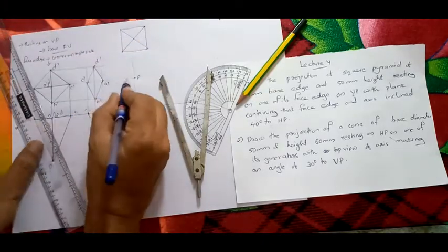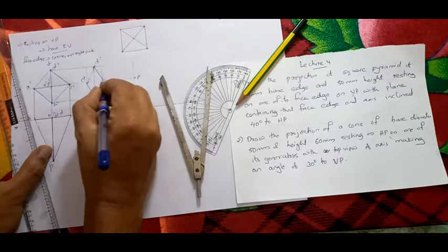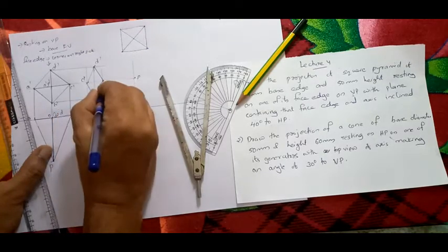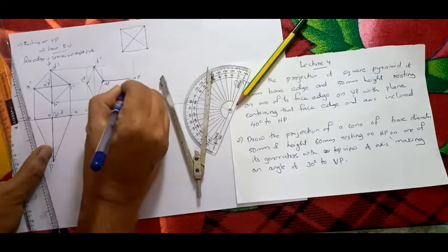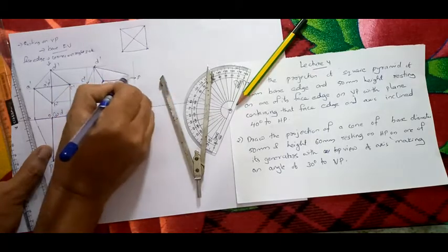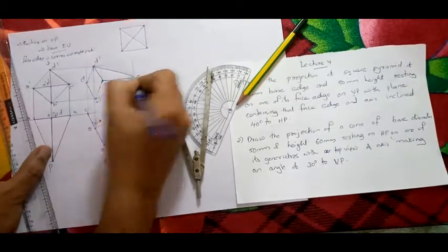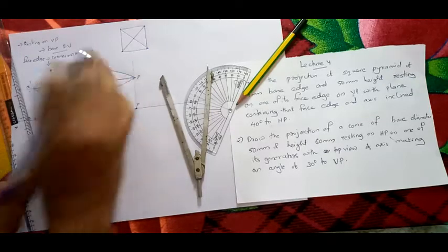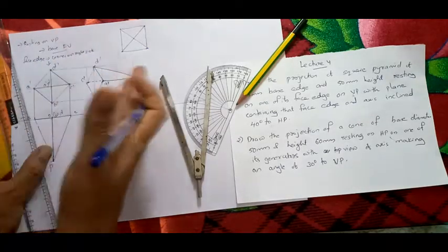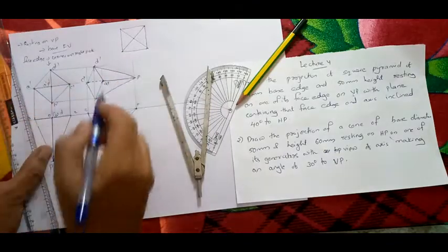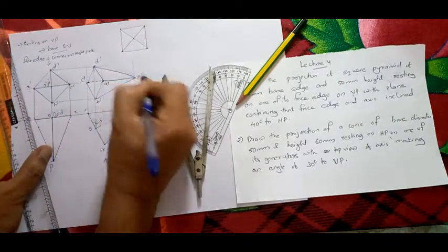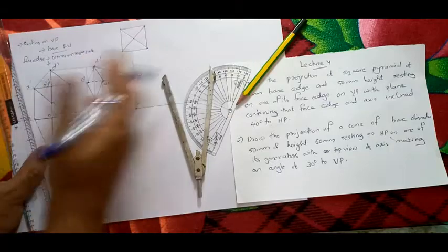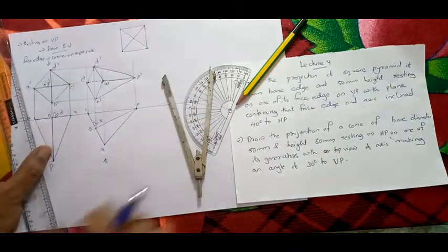Now the face edge, you have to draw face edges. See each face edge which is passing inside this square will not be visible. So AP is outside this base, right? DP is also outside the base. BP is also outside the base. CP is passing inside. So draw dotted line up to here only, because after A dash P dash is there, C dash P dash is behind that. So no need to worry about that.